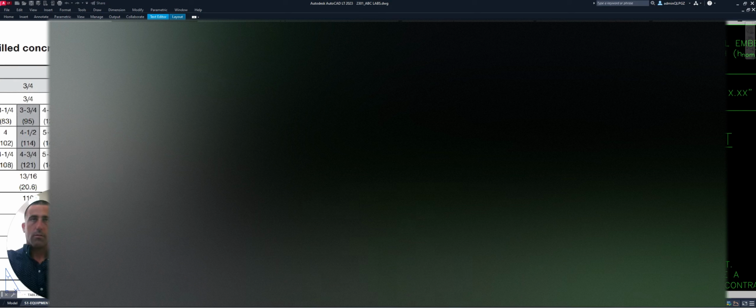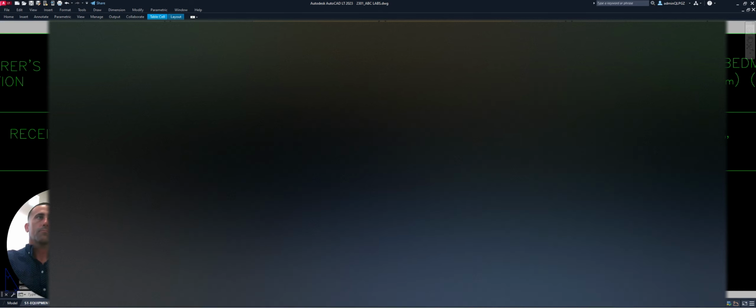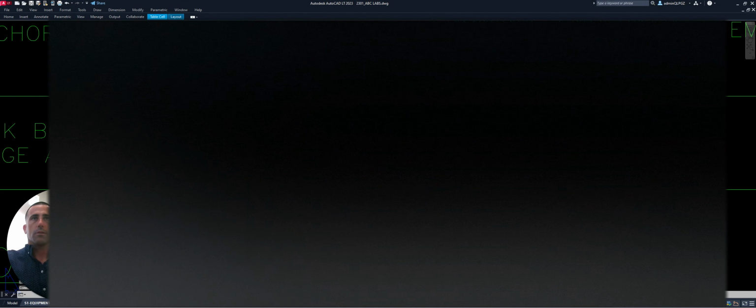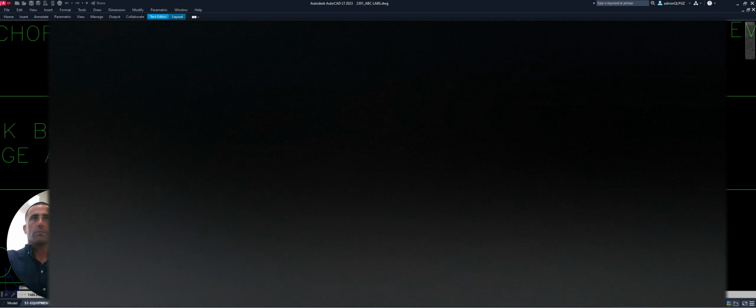And the weight of it is 1,671 pounds. And as we discussed earlier, the anchor type that we're using is a Hilti Quick Bolt TZ2-CS wedge anchor. The diameter, we're going to be using a 5/8. We're going to change this to 5/8. And there will be 4 of them.